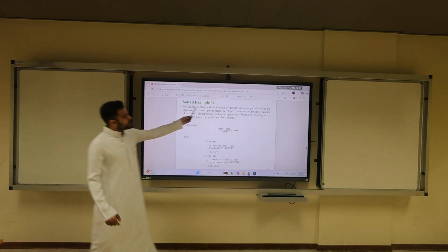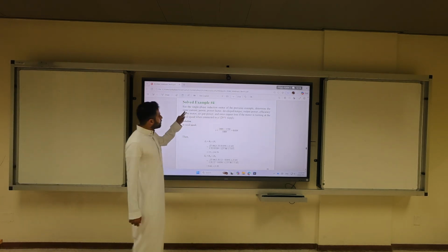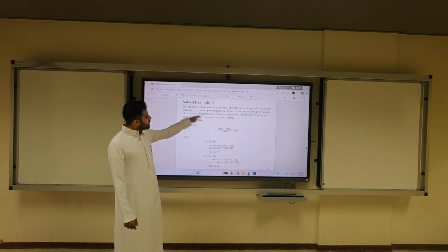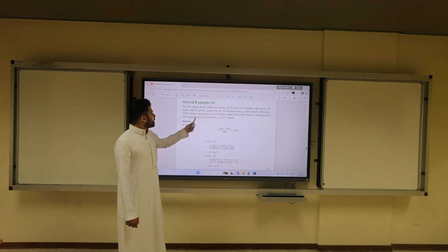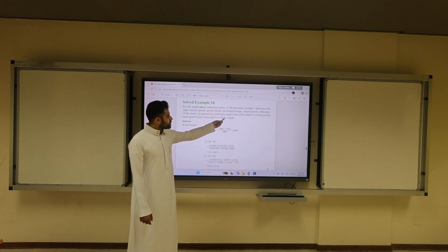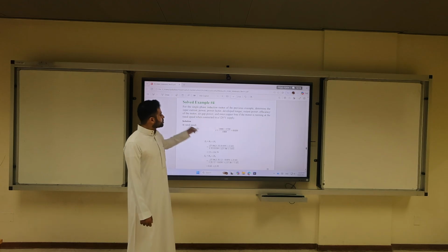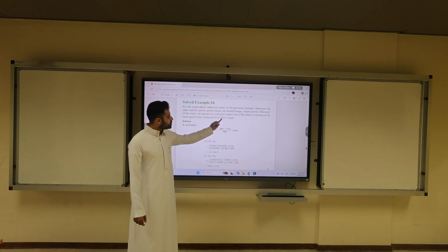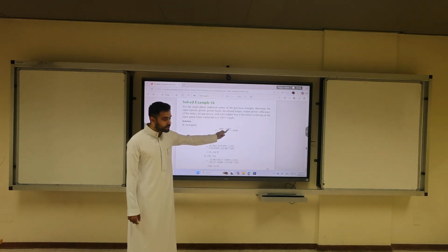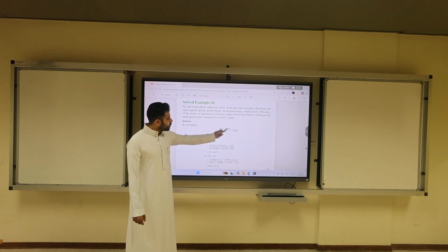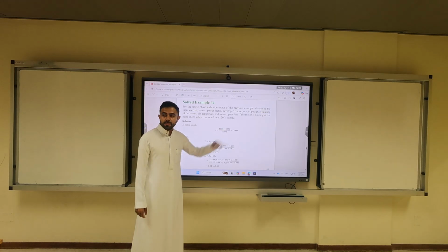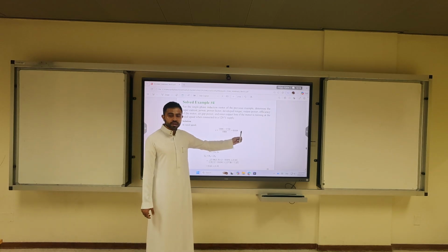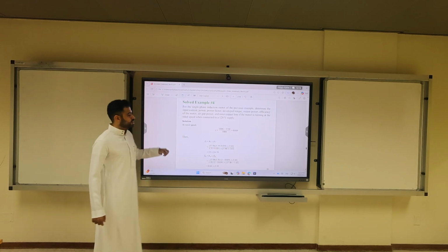So for the single phase induction motor of the previous example, find the input current, power factor, developed torque, output power, efficiency, air gap power, copper losses, when it's connected to 120 volts supply. So if you connect it to the 120 volt supply, you have to get first the slip, because 120 is rated voltage. If I connect it to rated voltage, I'm going to get rated speed. If you get the rated speed, get the slip, which is 3.9%. Keep in mind, I prefer always to add an additional digit in the exam to get more accurate answer.